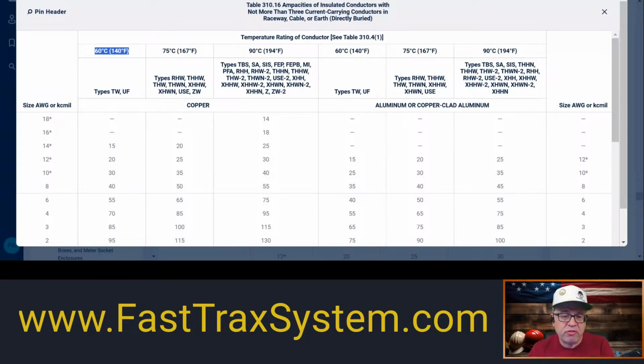Now, that brings us to an interesting topic when it comes to conductors. When you think about a conductor, if it is marked 75 degrees or higher, and even though when you're dealing with the 60-degree column, let's say for THHN, you may have an ampacity that's less than 100 amps, and you've got conductors that are 14 through 1, you typically would say, if nothing's marked, I'm going to use the 60-degree column, and that would be true.